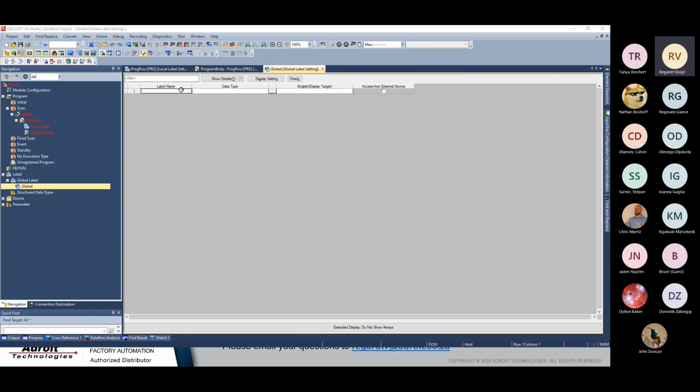First things first, we need to activate or deactivate the control systems. We'll call it the PLC start. This will be in cases where you want a PID controller to stop where it is. Let's say it's an emergency or a plant shutdown or whatever the reason might be. If you want the control system to stop, this will be your variable, and this will be a bit type.